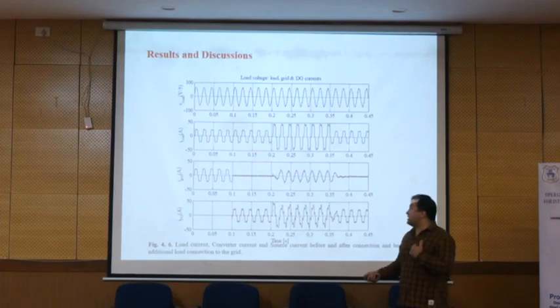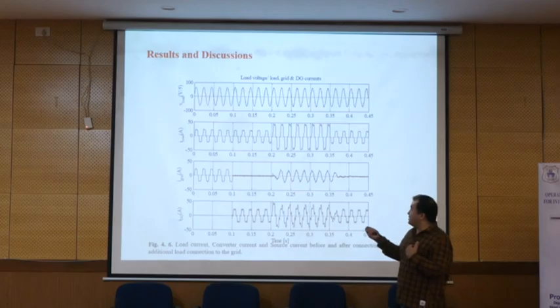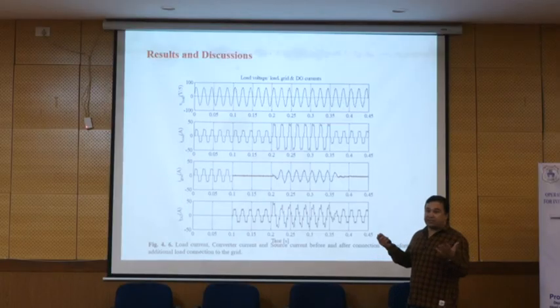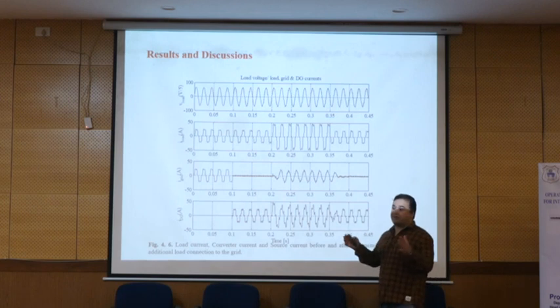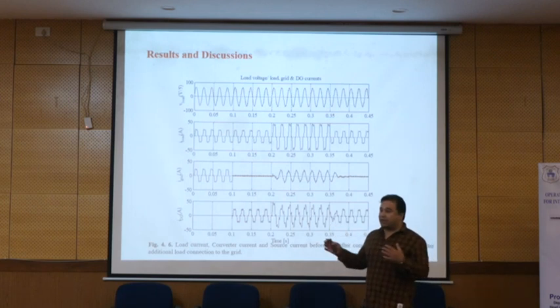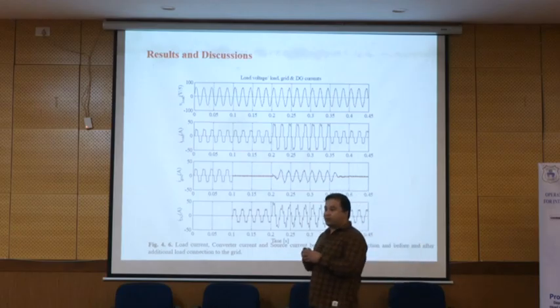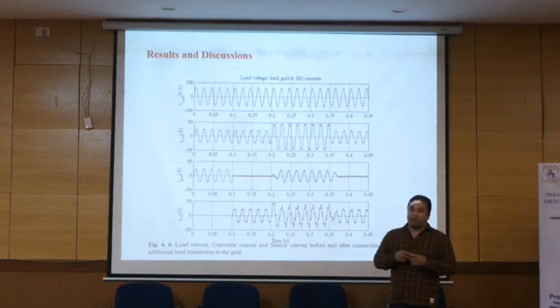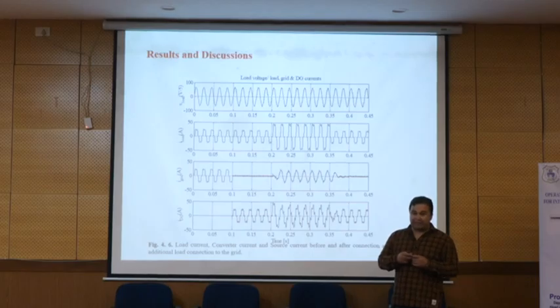So for this case, the rest of the power, which is the active power in fundamental frequency, is coming from the grid. So the grid can just provide the active power in fundamental frequency. The rest of the pollution, the reactive, harmonic, and some part of the active power, is injected by the DG. So, did you get it?